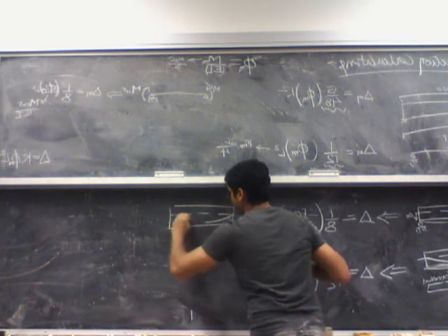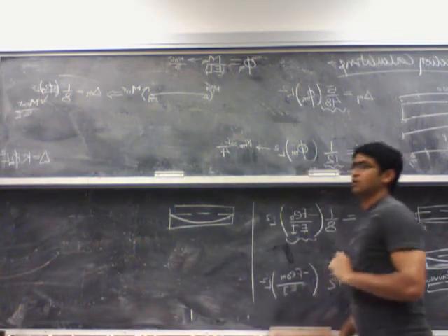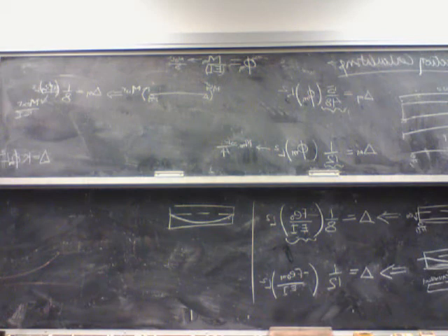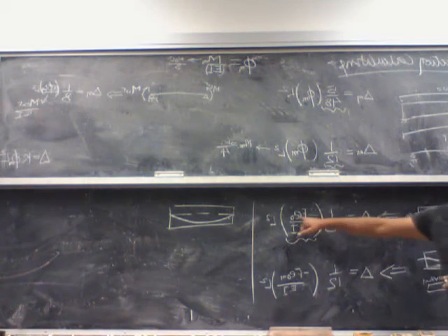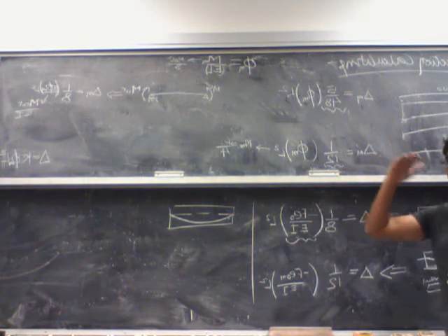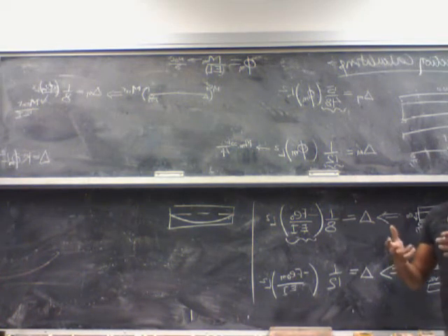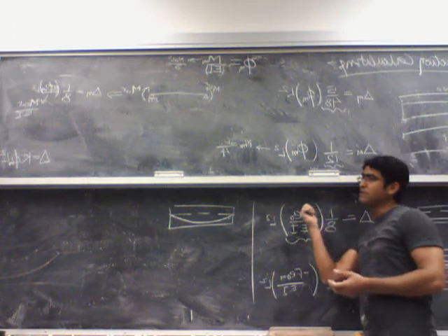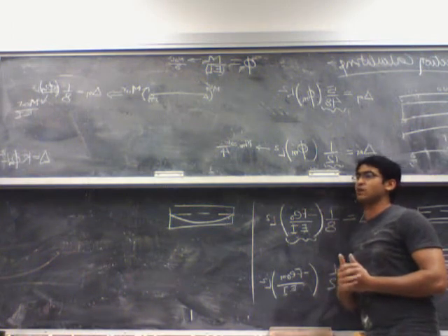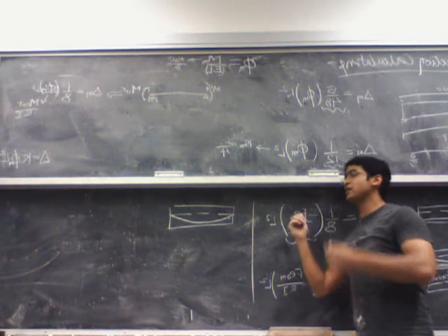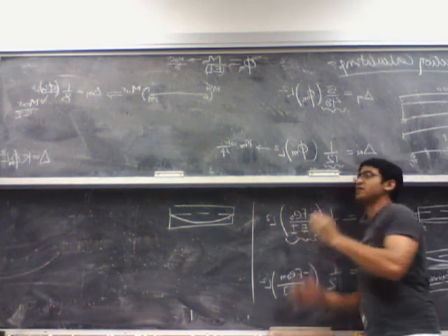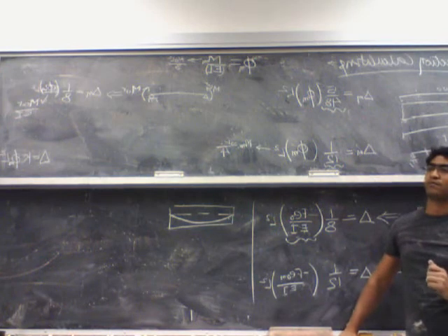when we have a parabolic tendon. Because if your e naught is positive, that means your e naught is below the centroidal axis. The moment due to the prestressing strand is actually a negative moment. So that's why you always add a minus sign in front of the F e naught. And so if e naught is negative, that means the tendon is above the centroidal axis, and minus F e naught directly gives you a positive value.